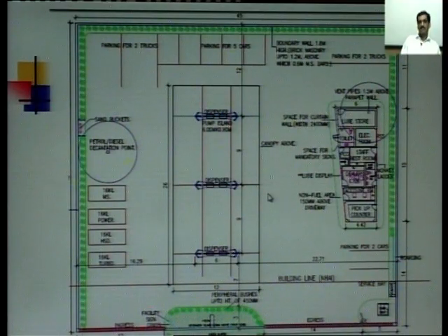So electrical, mechanical and civil are the major parts of a petrol pump which have to be taken care of. Take these machines: each machine has 4-5 nozzles at every outlet, and a normal highway outlet has 3 islands with 4 machines on each, and 6, 4, 6, that's 24 machines, and 24 independent wires running down to this electrical room.